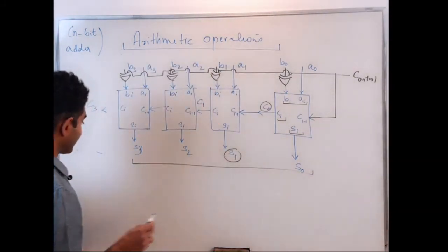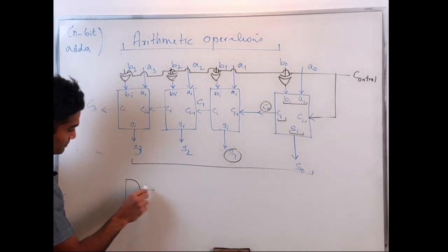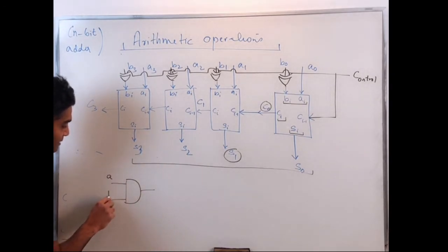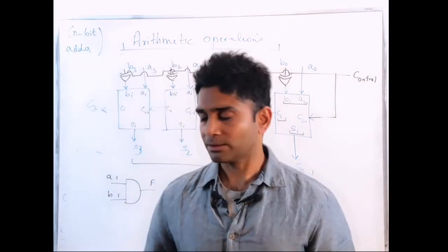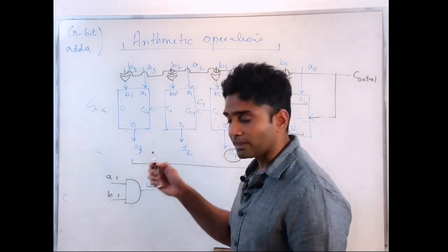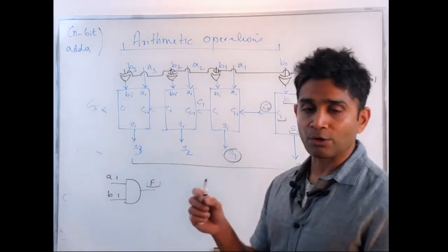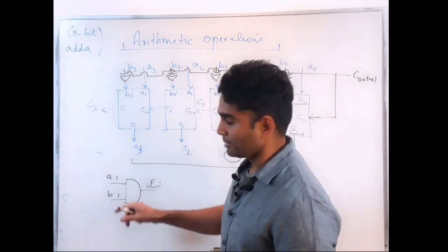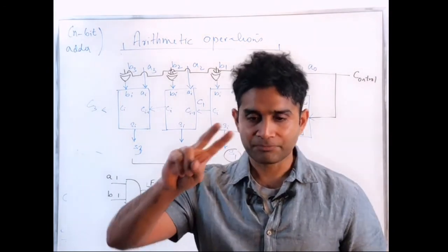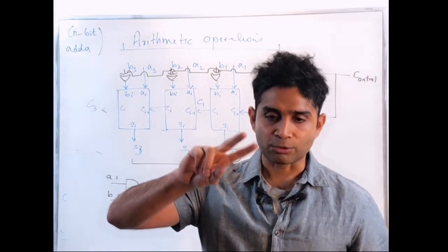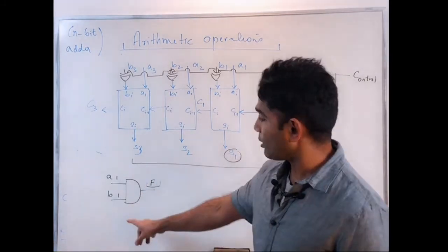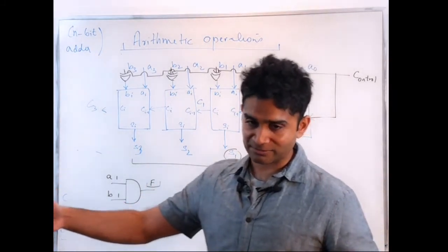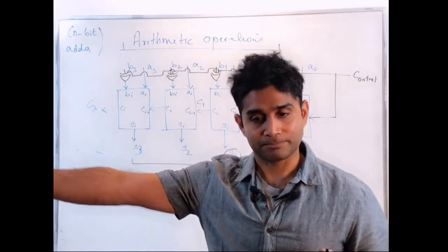That means if I have a gate, okay, I apply my inputs to this gate, I get an output F. As soon as I apply my inputs, I'm not going to get an instantaneous switch in the output. There will be some propagation delay, which we call a switching delay, because my gate has to switch from one value to the other, right? It has to either switch from 1 to 0 or 0 to 1, and there will be some slight delay associated with that. Of course, it's very small for a single gate, but if you have multiple gates cascaded, the delay can get added up.